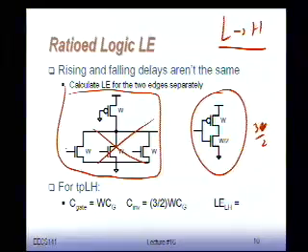Now what do we see here? You look at the input, we see 1W. That's what you see. The total capacitance of the inverter is 3/2 W. There's only one NMOS transistor connected. They have the same driving force, right? W in this case, W in this case, both of them are the pull-up networks. That's what we're looking at. So what's the logical effort of this gate for the low to high transition?